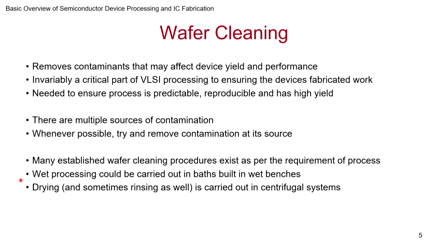Wet processing could be carried out in baths that are built into benches, wet benches, and they are under laminar flow showers, so there are no particles or dust coming from outside. So you make sure that whatever is on the wafer gets removed, and after it's removed, it remains clean. Similarly, you'll have a drying process, and sometimes rinsing as well, and it is carried out in centrifugal systems.